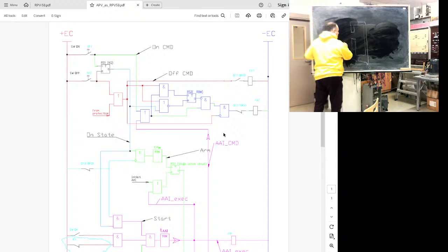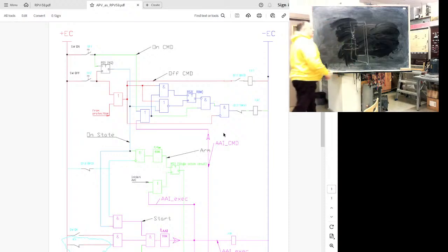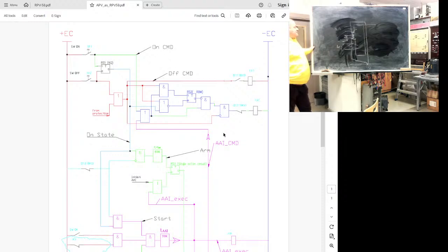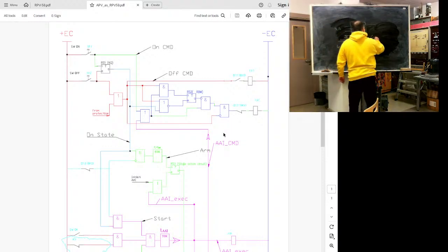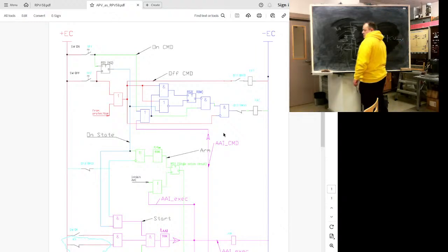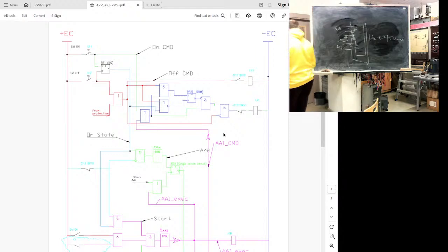Have a system like this. Coil 1, coil 2, and this kind of anchor. This relay yields 1 if the vectorial difference is less than the set point set by the spring.